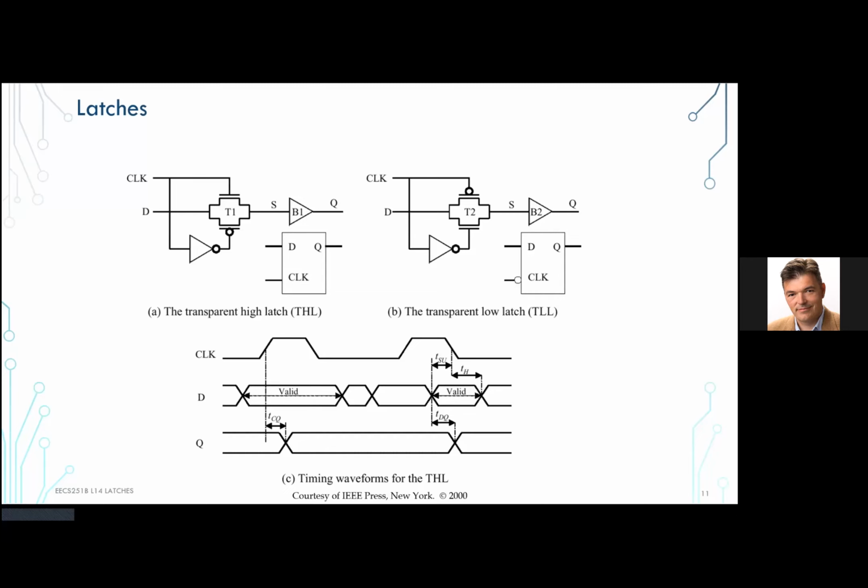But more related to what Ken asked me a little bit ago. I don't know what the logical effort of this gate is. It depends on who is driving, or which gate is driving this. So that means that the D to Q delay and the setup time are going to depend on what is driving.